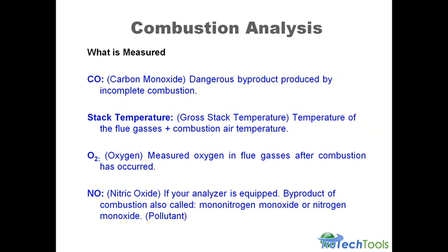So you're not talking about huge losses on a 90 plus by bringing in the outdoor air. In fact, the gains are actually much better because you're getting a better concentration of oxygen, and we're getting clean combustion air, which makes a big difference in the longevity of the appliance. So the gains far outweigh any small loss we'd have with a cooler combustion air temperature. And we could be measuring NOx or NO. That's typically something we'd measure in California where they are monitoring pollutants. These are nitrogen monoxides, and they're all pollutants.